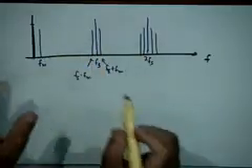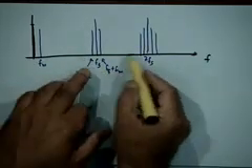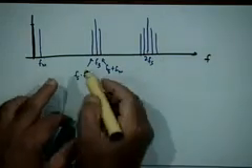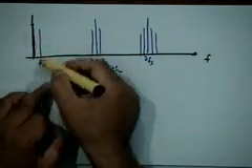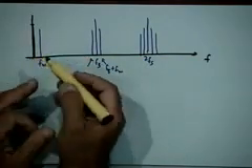However, the interesting and useful fact is that, as far as the baseband part is concerned, it contains only a DC component and the desired signal component, right? So what kind of spectrum you have around fs and 2 fs is not very important, as long as my baseband signal is intact. So to recover the baseband signal, what should I do?